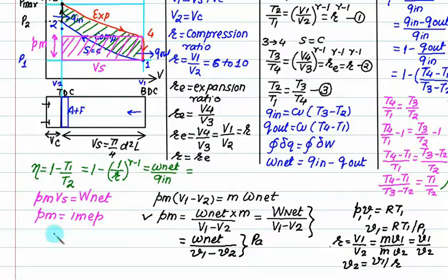So a 2000 cc engine is more powerful if the mean effective pressure is 8 bar as compared to the mean effective pressure of 7.7 bar, because it clearly indicates that the area under 8 bar is more as compared to 7.7 bar. In every cycle we generate more work.